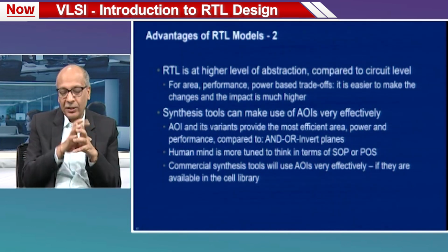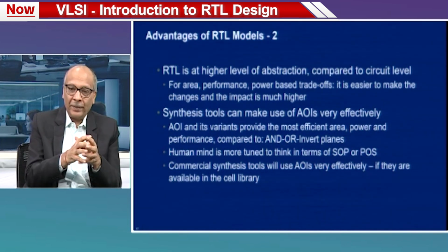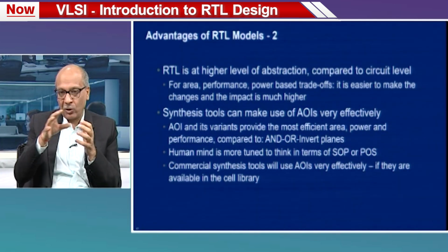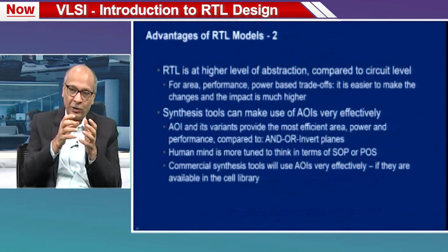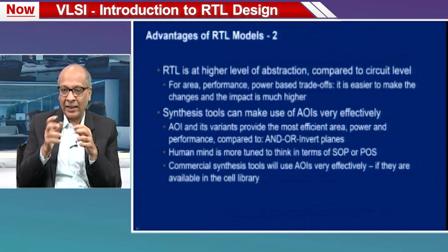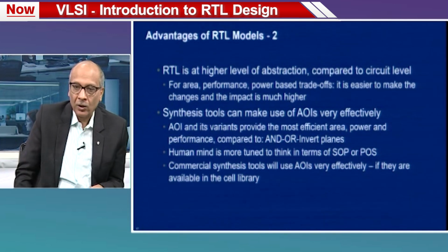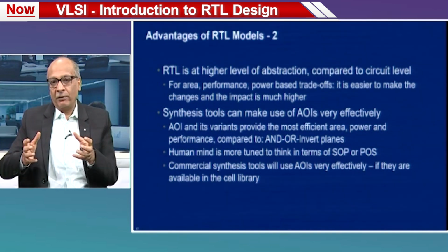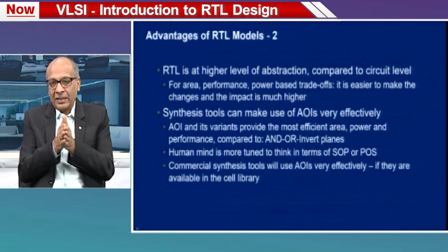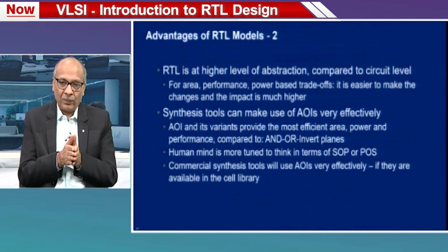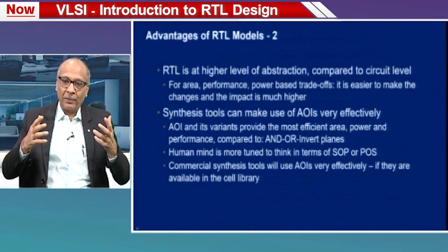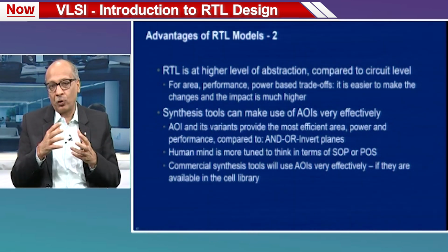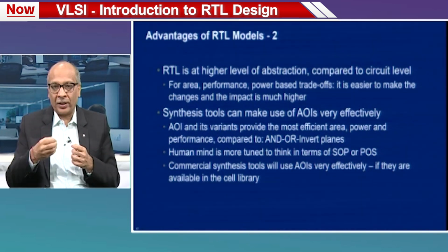So, synthesis tool can make use of AND-OR-invert kind of gates. I am saying its variants because you can create lots of variants. Instead of AND-OR-invert, you can have OR-AND-invert, or invert-AND-OR, and those kinds of things. So, synthesis tool can make use of a lot of these gates, effectively realizing a functionality in much lesser number of transistors. Okay. We human beings are not used to AOI style thinking. We are much more used to thinking in terms of AND gate, OR gate kind of thing.